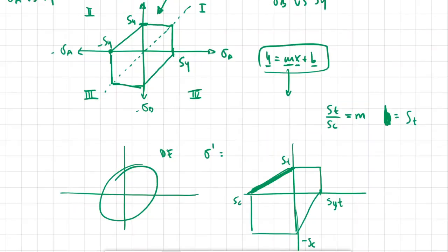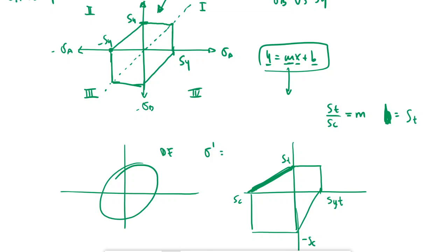Basically, all you want to do for these 3 cases, this is for ductile materials, is that your stress state, your sigma a and your sigma b, be within this geometry. Okay, you want to be here, here, here. As soon as you go out of this geometry, no matter in which quadrant you are, the material is going to fail. Right? Again, there's plenty of examples here. There's homework. There are some quiz solutions that go over this. The night exam had this, so you can look at that solution if you still have questions about this. Right?